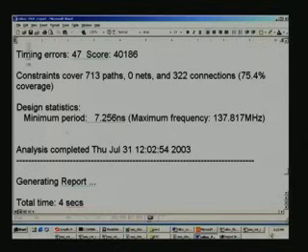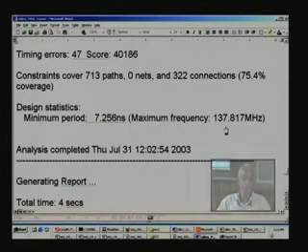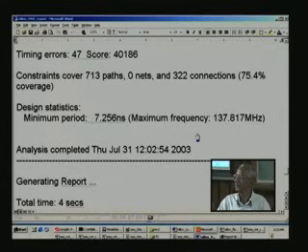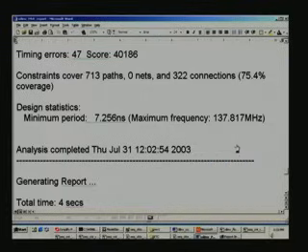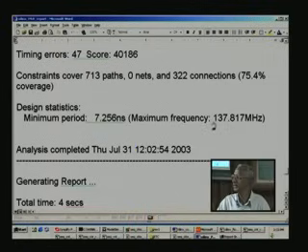And here comes the frequency of operation. You see it is surprisingly higher here. As I mentioned, for a smaller design my observation is synthesis will be very conservative, but real designs are all big, so it will be the reverse. Normally synthesis will report say 100 megahertz, but place and route can give only some 80 megahertz. That is the usual scenario, whereas here it appears to be exactly the reverse, and I think we started with 116 megahertz in synthesis.